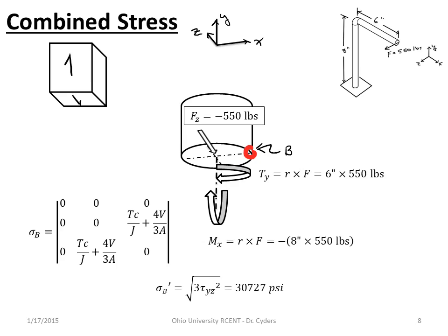If we have a constant transverse torsional stress, and then we have a transverse shear and bending moment that are just like a beam problem, we remember that the bending moment stresses are generally going to dominate, and as a result, the transverse shear and the way that it combines with the torsion is still probably not going to be enough to outweigh that bending stress. Regardless, we can quickly see, just by picking a couple of points, the different stress distributions and their sum total effect on that given element.